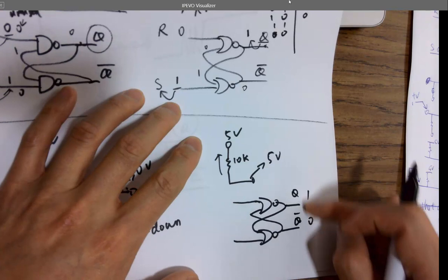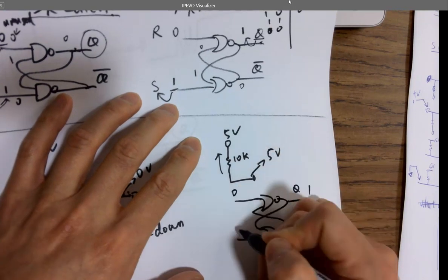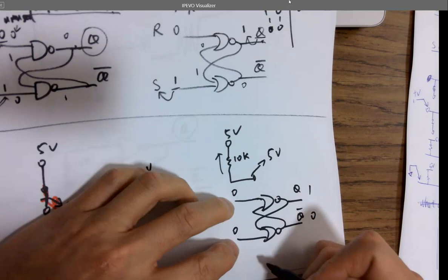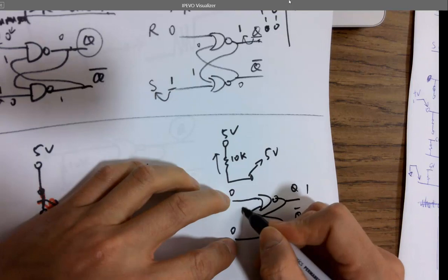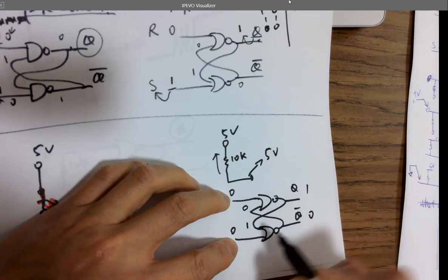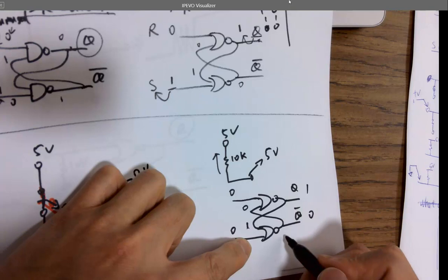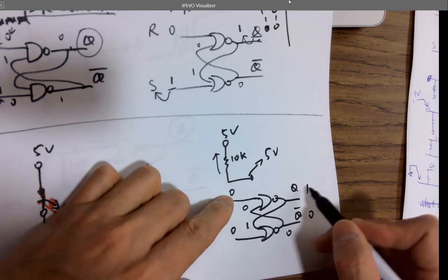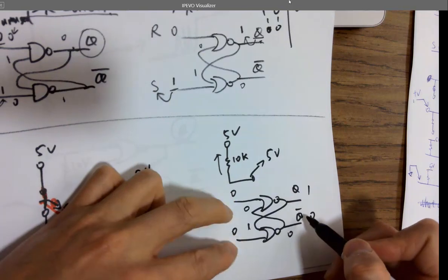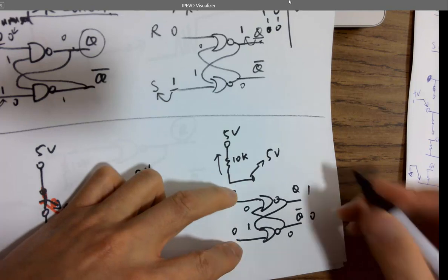As a previous state, 1, 0 like this, okay? If we give a 0, 0, what's going to happen? 0, 0 to the NOR gate SR latch. So this was 1, 0, so 0 will be fed back here and 1 will be fed back here. So 1, 0 NOR is giving you what? So these two are giving you 0. And 0 being fed back here is giving you what? 1, right? Is that stable? It's not flipping anything, right? It's stable.